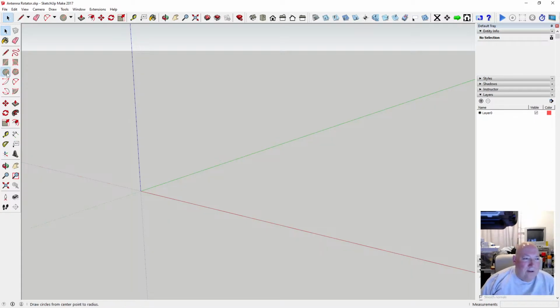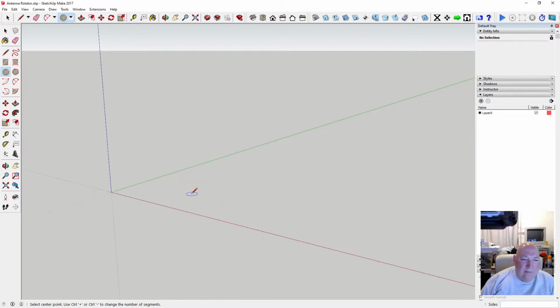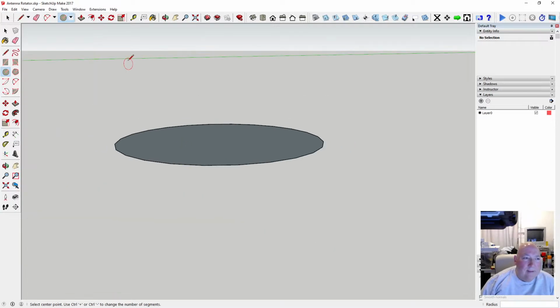So we'll start off with the aluminium tube, because we need to form a bearing around it. I'm going to say 40mm aluminium tube for now. And I'll say it's, I don't know, 2mm thick. Let's say 2mm, that's quite a lot.